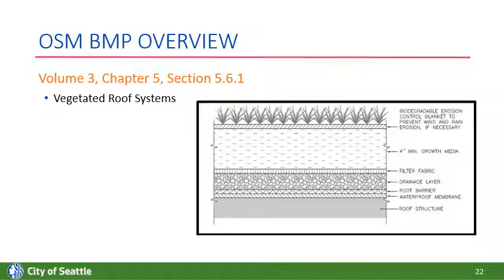Added are irrigation requirements, a minimum of 5 growing seasons. A note has been added to clarify fertilizer application on vegetated roofs. And removed is a restriction on fertilizer, pesticides, and herbicides after the 2-year plant establishment period.